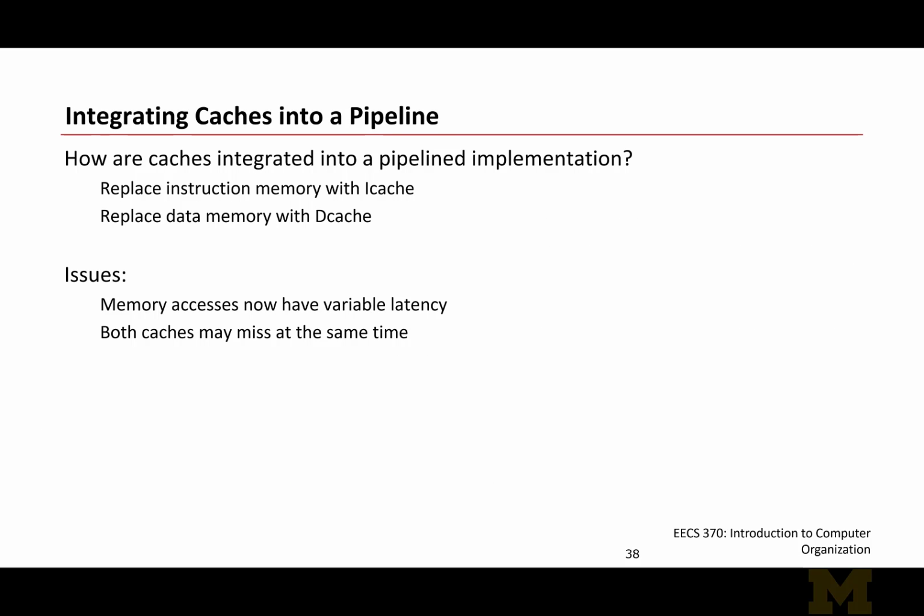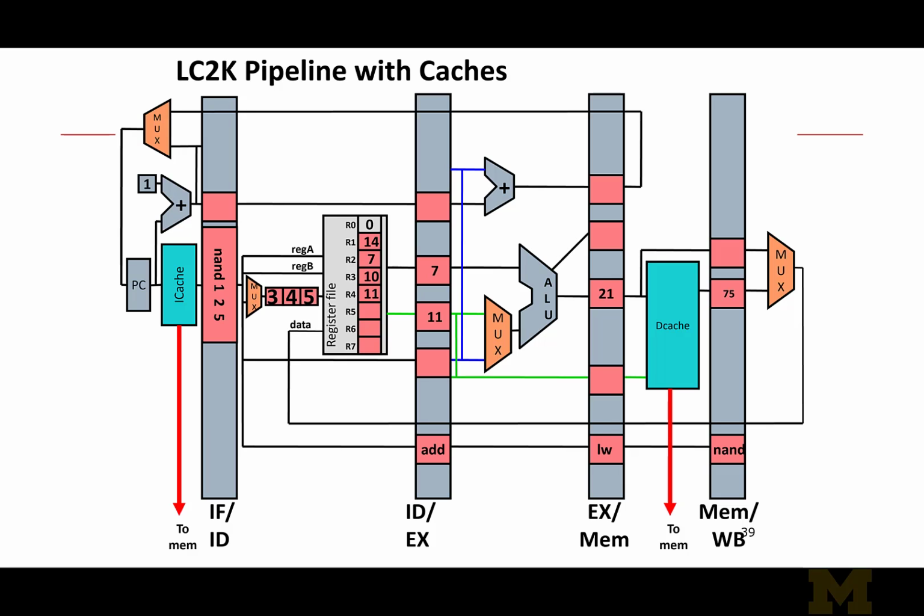If you look at the pipeline diagram, now we can replace the structures with our instruction cache and data cache. So now these are a little bit more realistic representation of what an actual processor looks like. And the instruction cache and data cache, which are level 1 caches, operate at the speed of the processor clock cycle. So if you assume that the processor clock is 1 gigahertz, they can operate at 1 nanosecond, and so you would not observe any extra stall than what we had already assumed in our pipeline design.